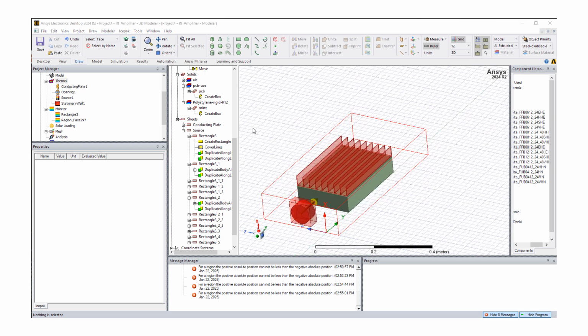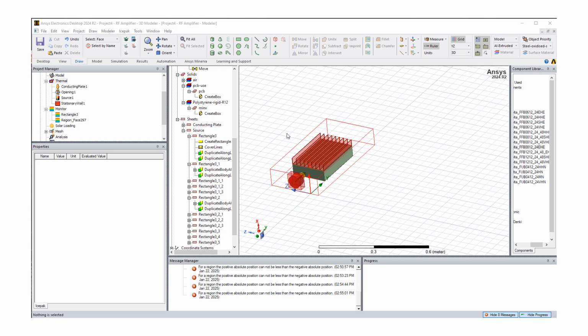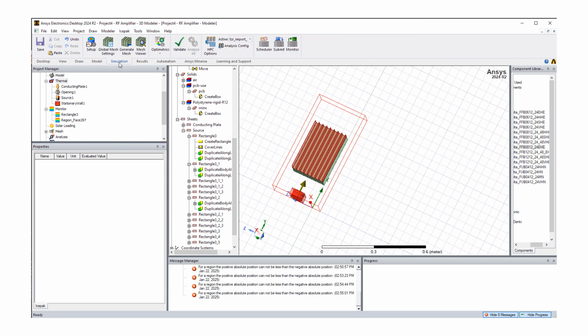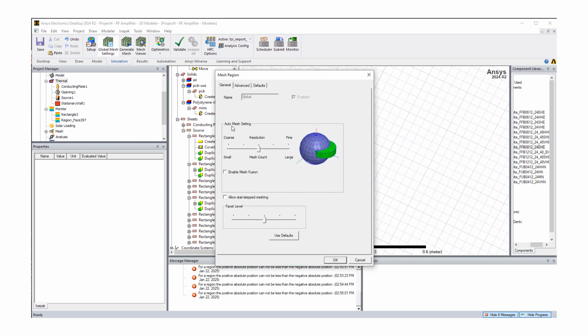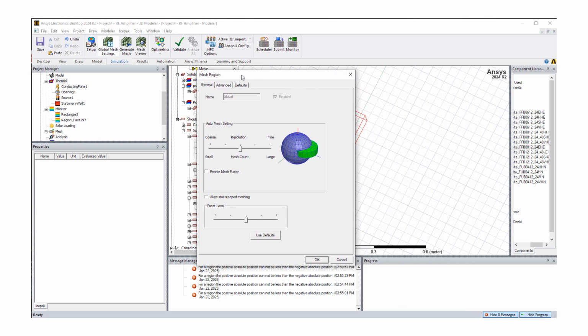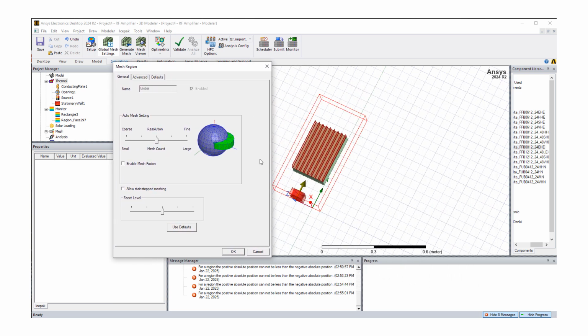Next step is meshing. Now in AEDT Icepak, let me quickly show you the meshing option. So we go under Icepak. If we click on simulation, we have essentially two different approaches, I would say. One is to use the automated mesher, which most likely will work pretty well for this particular geometry because it's fairly simple shapes, nothing overly complex. And one could typically set a resolution. Usually I would suggest 4, maybe 5 levels.